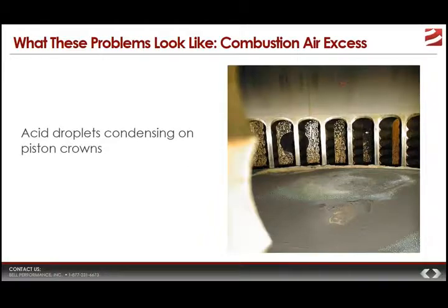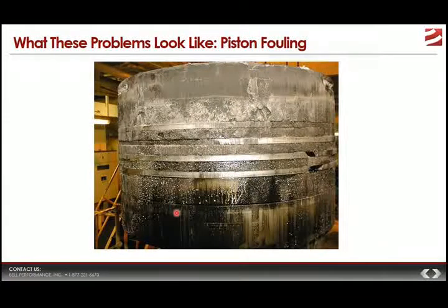And so this piston top is much larger than the average person is probably used to. In fact, you can see even better the scale of what we're talking about here, because this may not be the same piston, but it is another example of a piston. You can see all of this fouling. You can look at the flaking and the metal damage that's happened up here.